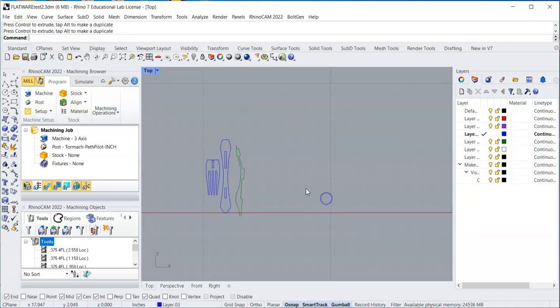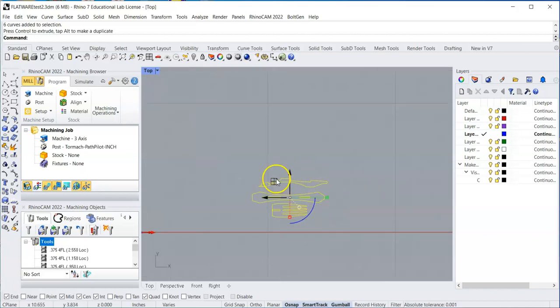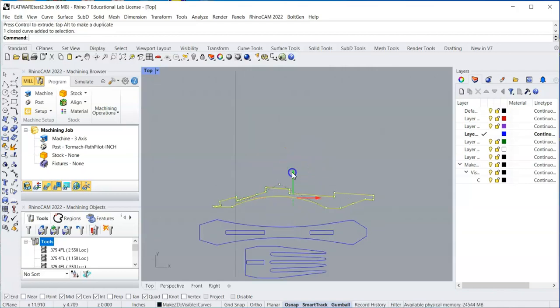active, right? Now we know that our mill has a longer capacity in what axis? In the X, that's right. So what should we do here? Rotate, that's right. We should rotate it. And that'll assure us that we are cutting in this long direction we have, since we have less room in the Y. Now, a couple of things I could do is I could go ahead and I could start to nest these, right? If this is hanging out over here, it would just make sense that I would kind of, you know, move that over a bit.